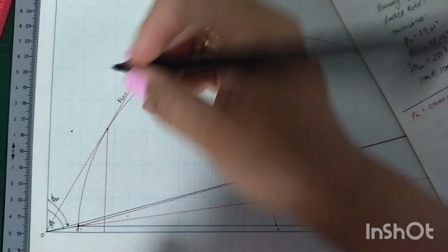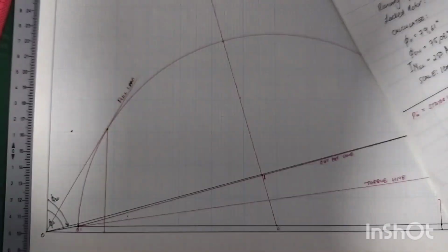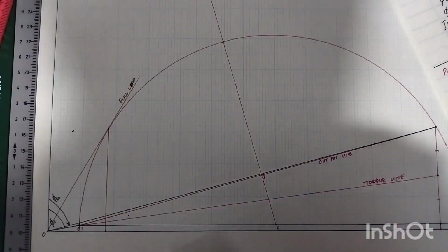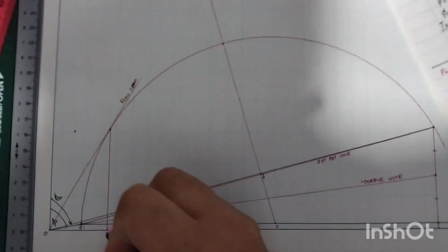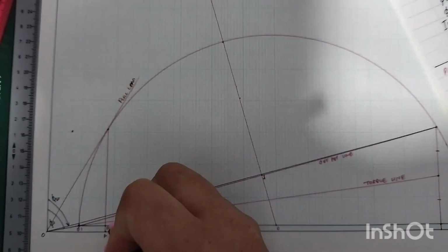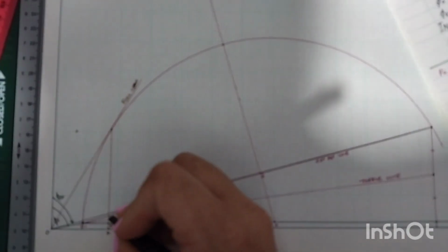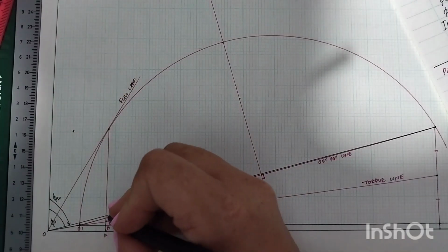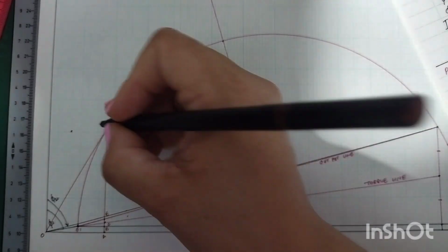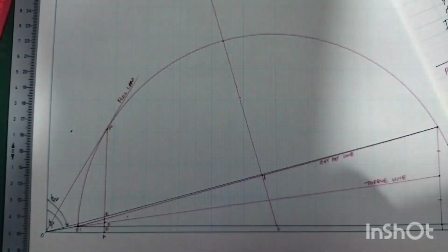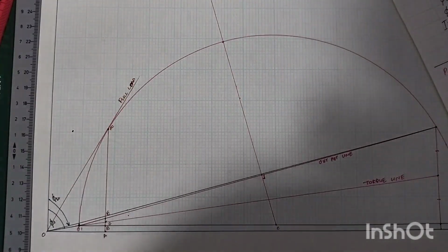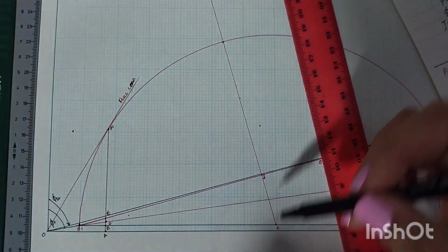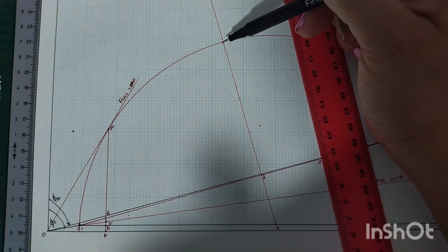So you are going to mark out the point on your base or your horizontal axis, the point in your new horizontal axis, the point on your torque line, the point on your output line, and the point on the perimeter of your circle. You can call it whatever you want to. I like to stick to the letters of the alphabet. C is the center of my circle, so I'm not going to use C again.